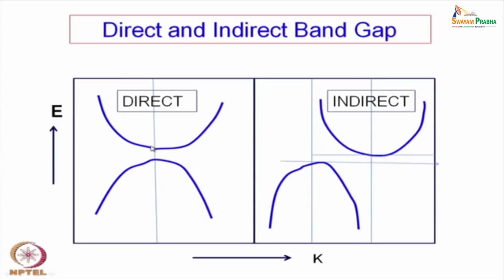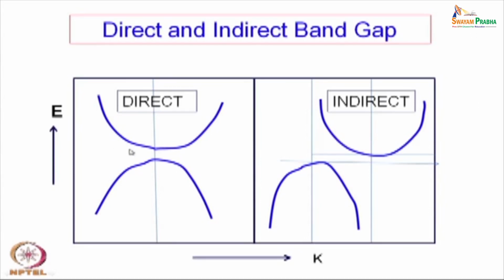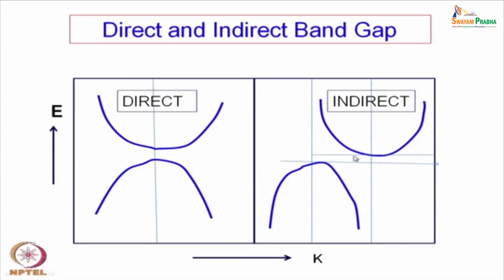and normally if you have to draw a band diagram of this solid, we will draw a horizontal line like this and we will draw another horizontal line here. Okay. So, that will represent the band gap for this material. Here also we have just drawn two horizontal lines, one is this one and there is this one, and this is the band gap. So, we do not draw a curve, okay, and we are not concerned with what the band gap is away from their maxima or minima.